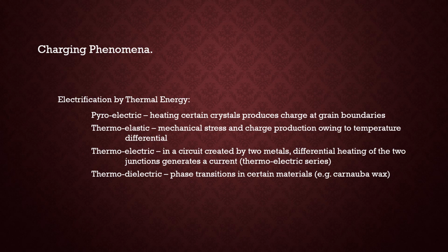So there's pyroelectricity, thermoelasticity, thermoelectric. They're all quite related. What you're doing is essentially replicating that mechanical stress, the piezo I mentioned previously, by thermal means. So you're causing movements of the charged particles within the material according to a thermal gradient.